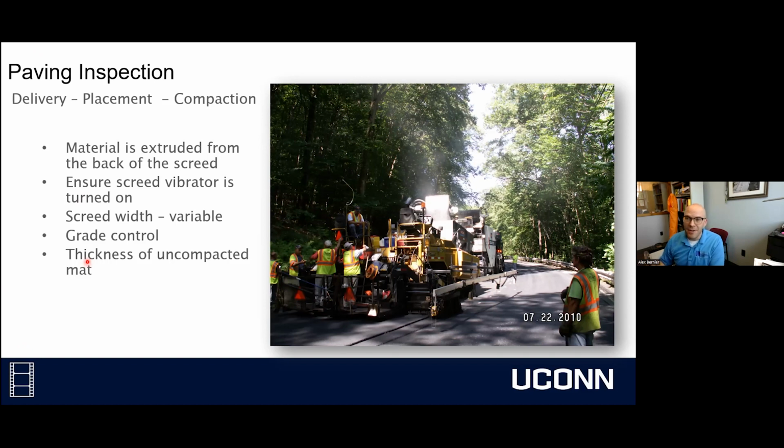So that's the paver. It's the moneymaker, right? Without the paver, we really aren't going to be placing material in a uniform way. And what we're looking at here is a crew placing an original lane, right? So you can actually see the joint being constructed here with the mobile reference beam. So this is perfect. This is the other type of technology you would see on a paver.